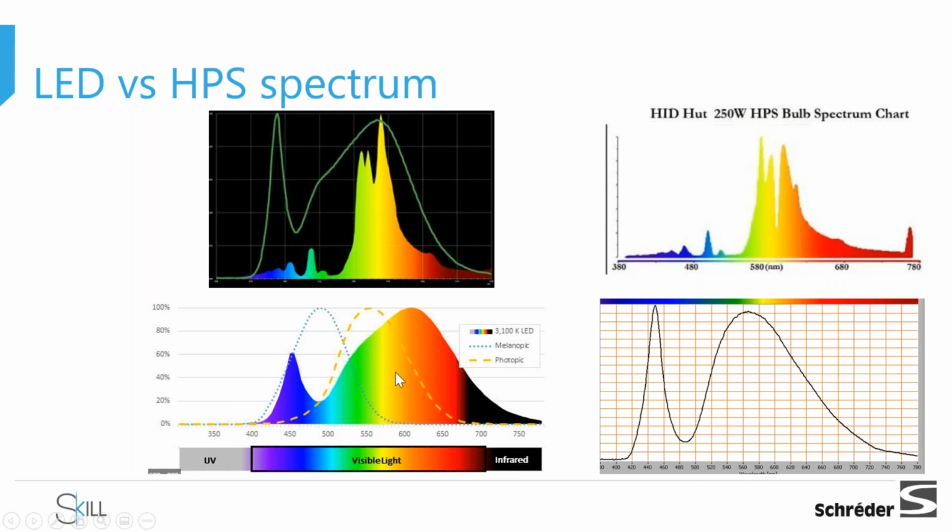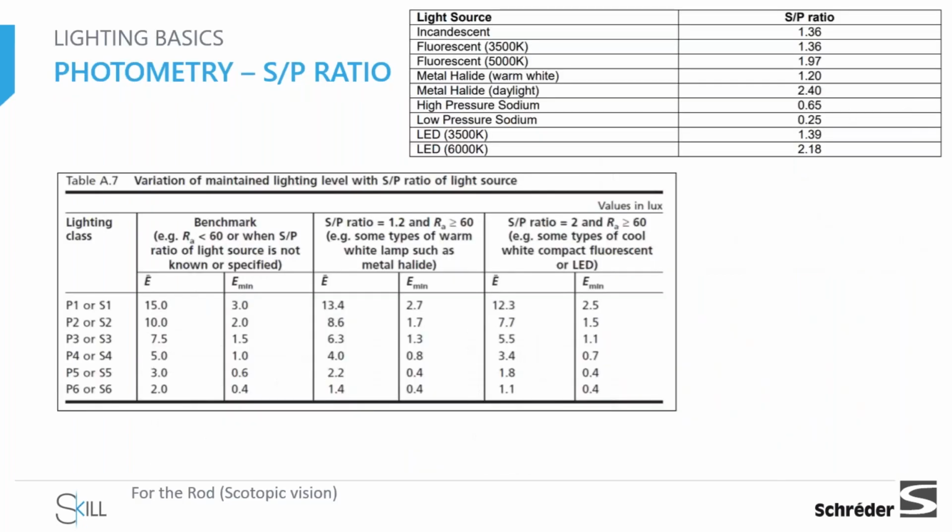And as the eye sensitivity during the night is shifting toward the bluish, we expect that at the same light level at night between high pressure sodium and the cool white LED, the eye will be more sensitive toward the LED.